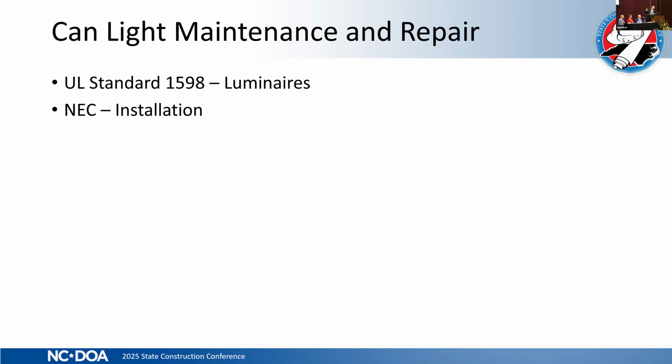The NEC is also going to address this luminaire issue. The UL is going to tell you how it's built for construction, for mechanical, for those kinds of issues. As far as I know right now, it still doesn't address the aperture issue. The NEC requires some specific things about the fixture. Any box that is installed, we need 3 inches of wire to come out of the box.